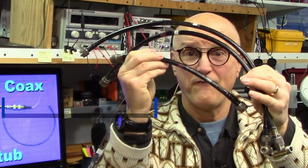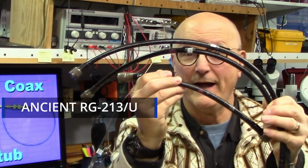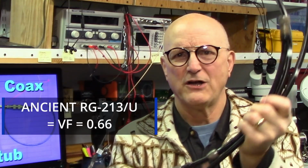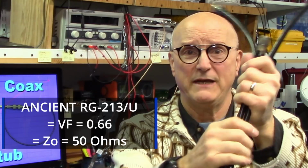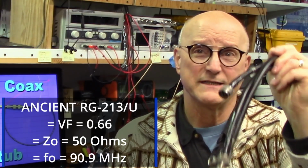So for this demonstration, I know that my system is made up of some very, very old RG213U coax. According to the data sheet, the velocity factor of my coax is 0.66. The characteristic impedance is 50 ohms. The frequency of interest is 90.9 megahertz.